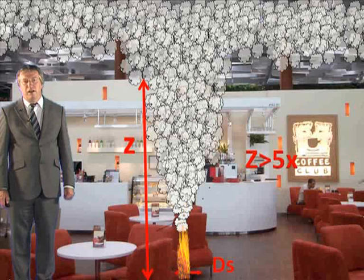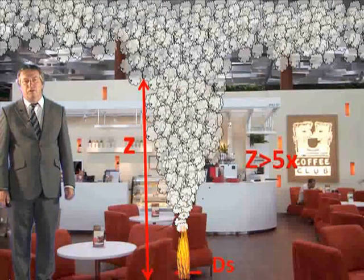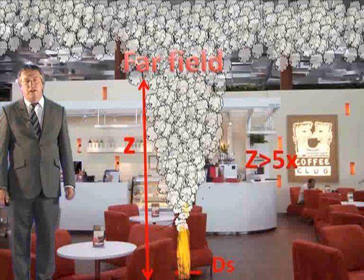Don't forget that if the clear layer height Z is greater than 5 times the longest dimension of the source fire, then this is often considered to be in the far field, and otherwise we would use a near field model. However, I should point out that this varies depending upon which publication or research paper you're reading.